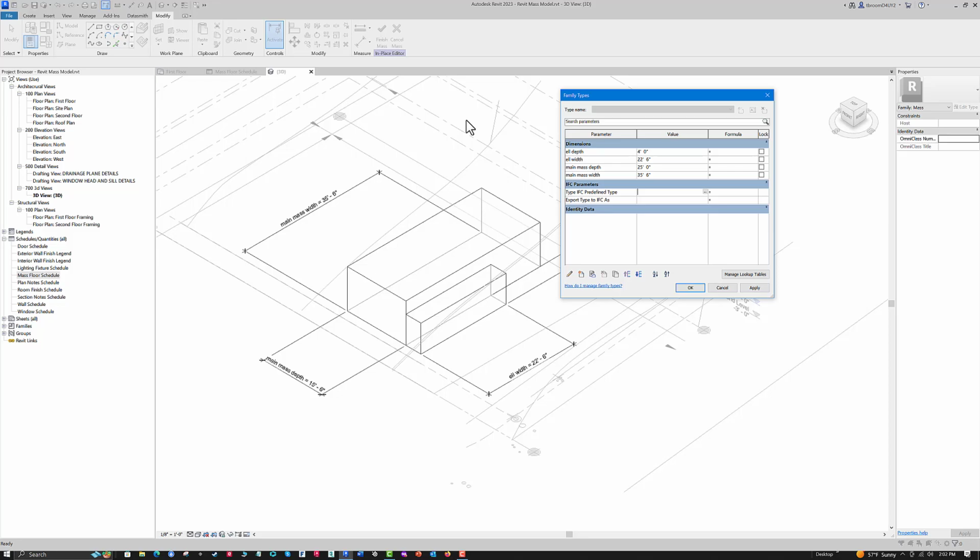So when you're working with brick, you want to always make sure you design to a brick module, and in this particular case here, I'm going to be using a standard brick, so that module is going to be a 4-inch module, which means that all my dimensions have to be divisible by 4 inches. And the way I do that is very simple, really. I know that all even feet will do it.